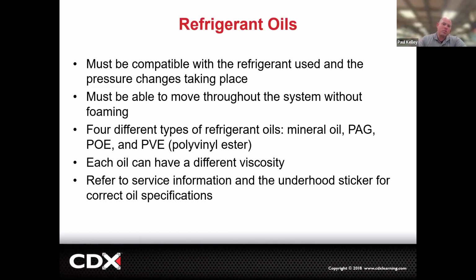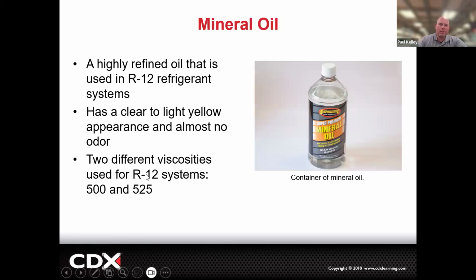Okay, PVE. Each oil can have different viscosity. So you can have low, medium, or high viscosity PAG oils. Depends on what the car calls for. How would you know what to use? The sticker, remember? Remember the sticker? The sticker will tell you. Refer to the underhood sticker. Cool, that's why I pulled that in there.